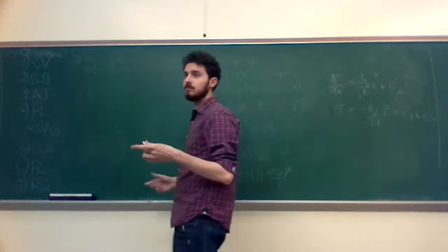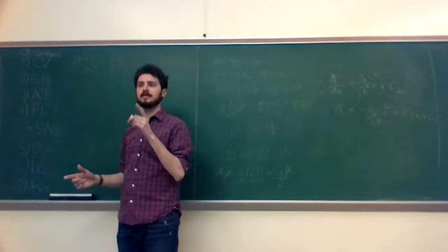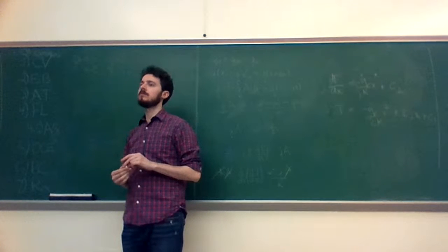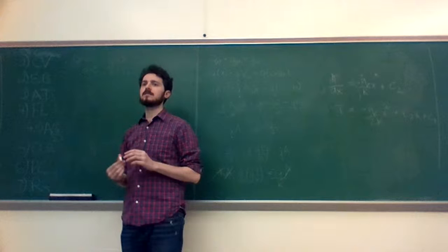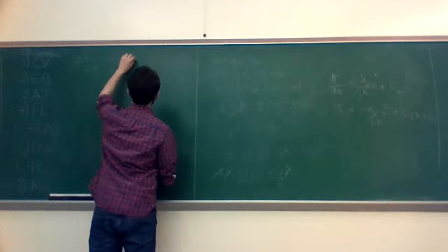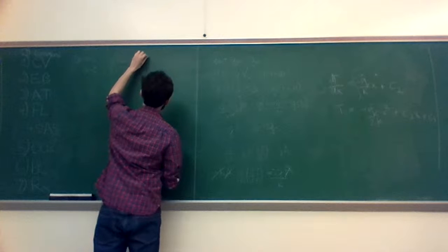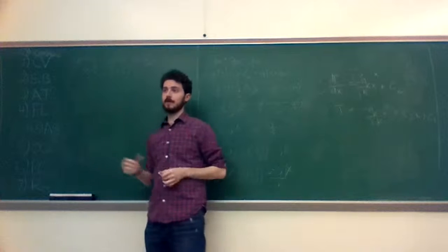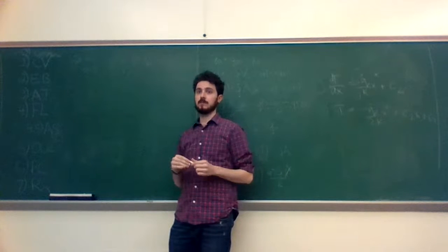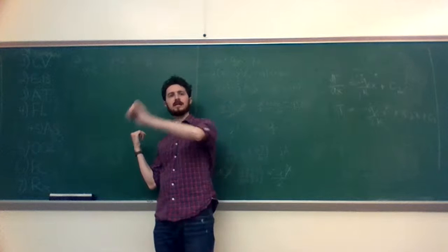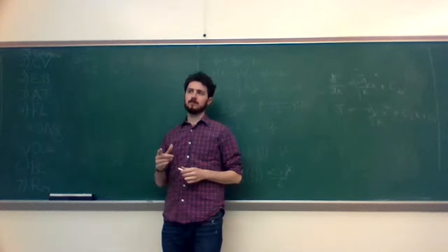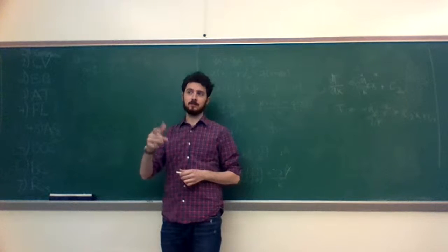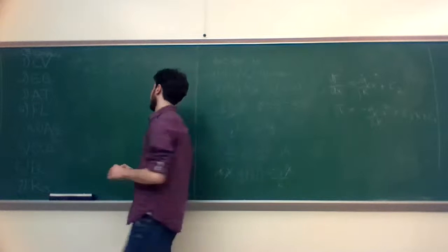If q equals 0, and q is negative k dT/dx, and k is constant, then what does that mean also equals 0? dT/dx. So if q equals 0, that implies dT/dx equals 0. There is no slope, no temperature gradient at that point, at the origin, which we already discussed at the beginning. That's how we got the shape of that curve. Sound okay? Yeah? We have a question. I understand it now. You understand? Okay, yeah.